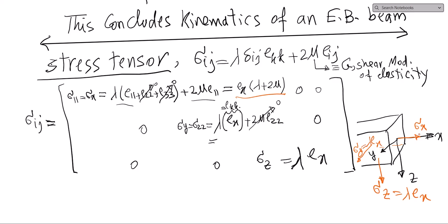We will see that these two will be very small when I write it in terms of Poisson ratio, and I will do it soon. But let's make sure that we understand this. The only component that in terms of magnitude is important is this sigma x. The other two come because of the Poisson effect, which is the stress normal to the plane in the y direction and the stress normal to the plane in the z direction. And these two also survive.